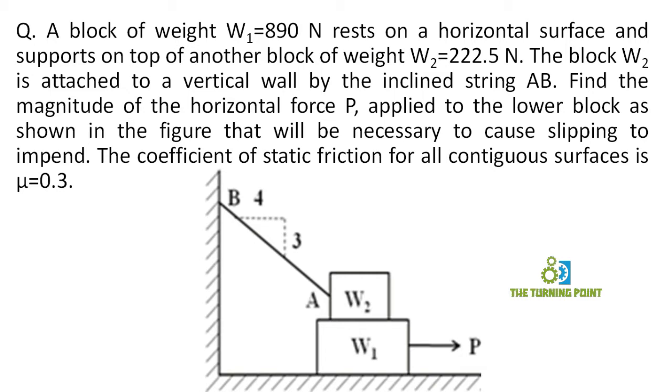For solving the problem, we need to draw free body diagram and apply equations of equilibrium. This is the common procedure adopted for any kind of problem, generally in friction. So here, as there are two blocks, you may ask me which block we have to start with. So when we consider these two, the force is applied to the block 1. Because of that, it will tend to move in positive x direction. The impending motion is there for block 1 first. You need to start with a free body diagram of block 1. Let us start the solution.